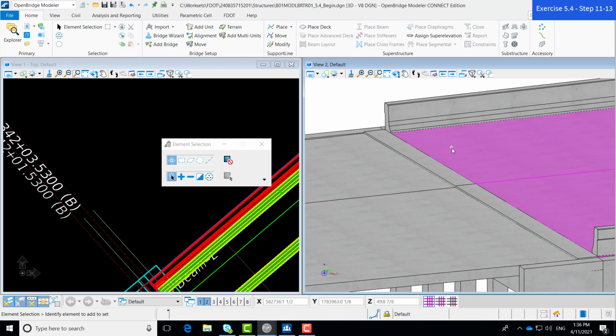We have the 28-foot span that's just a little bit lower, and we have our 2-foot span that matches the elevation of our main span deck. So the last components we have to add to the bridge before we have completed this exercise will be the barriers. So remember from exercise 5.2, there is a template. In this case, we're going to be using the F-type 32-inch barrier. So there is a left and right barrier template that's selected, and each of those templates has a working point, which is going to match a point on the deck.